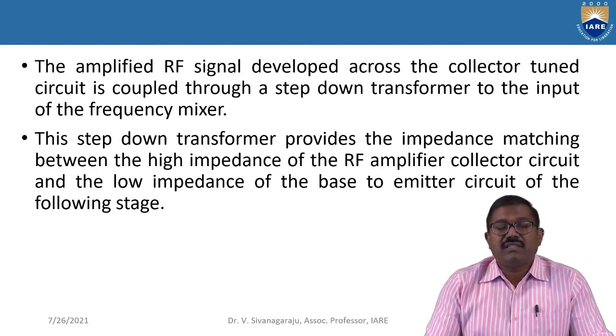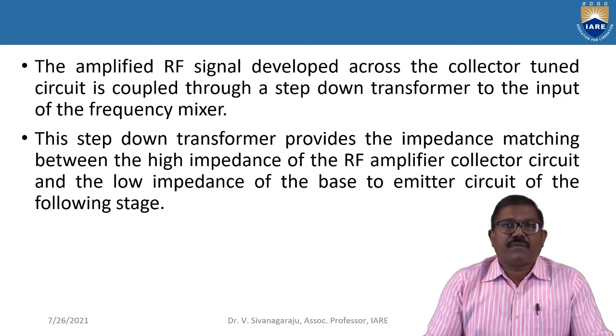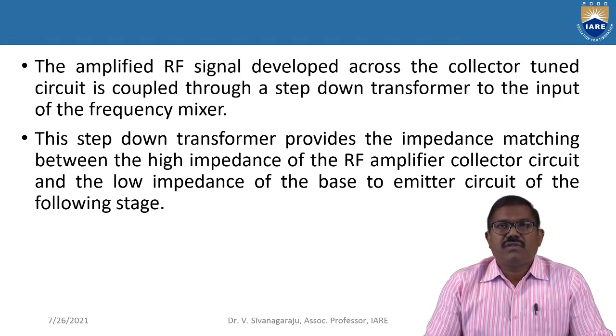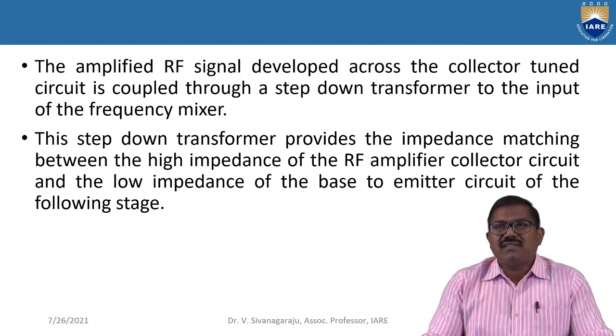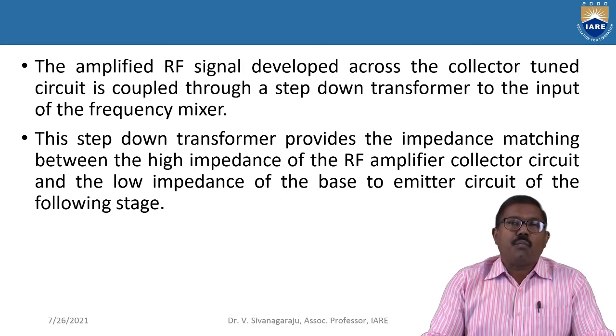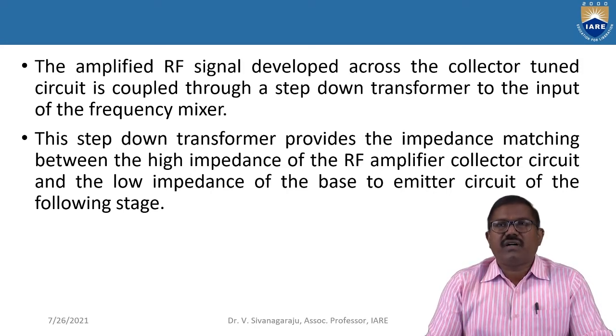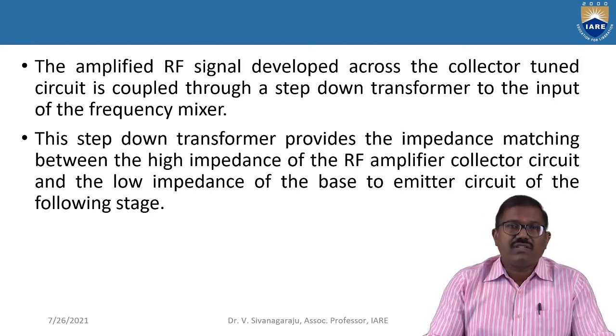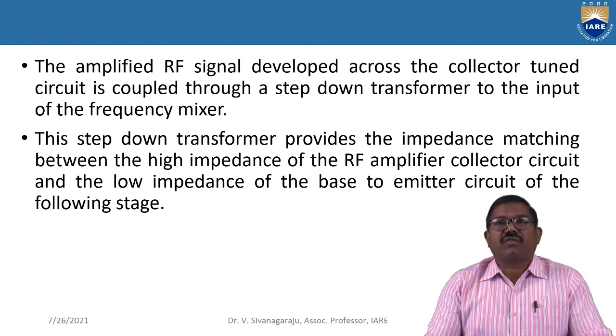So in this circuit diagram, we can see the transformers. The step down transformer provides the impedance matching between the high impedance of the RF amplifier collector circuit and the low impedance of the base to emitter circuit of the following stage.